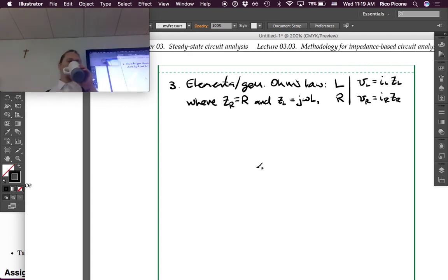Good. So, here's the first little nuance to the steps that I will add in. I recommend not plugging in the impedance values here until the very end. Otherwise, you gotta bring all these complex numbers around with you. You don't want that. You don't need that. It's better without it. So I just leave it as ZR and ZL.